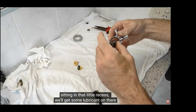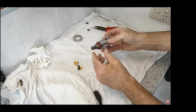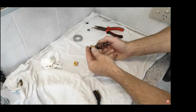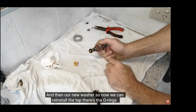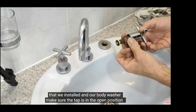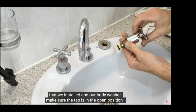That's because the jumper's not captured and it's kind of falling out. Sometimes you can find a thicker jumper that will just go in there, or if you take it outside and tap it with a hammer, it makes it slightly oval, so it squeezes in there tighter and can stay there. Yeah. Looks like a Chroma tap set.